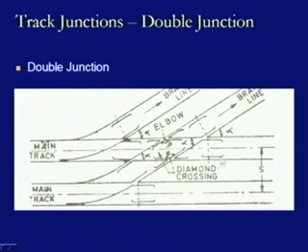We have two main tracks moving side by side with each other, and what we find is that there is one turnout which is coming out of this main track, and it also crosses the other main track and then goes like this. So, it is creating a diamond crossing at the location of the other main track. So, this is the location of a diamond crossing at this point, and this is what is termed a double junction. So, there is one junction here, there is another junction here, and that it goes away, whereas in this case when it is going like this, it is a simple turnout, a left hand turnout.